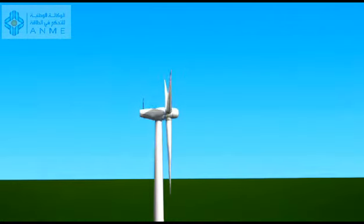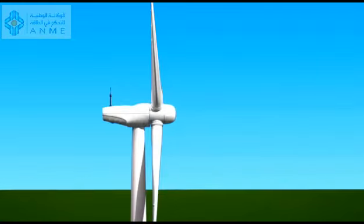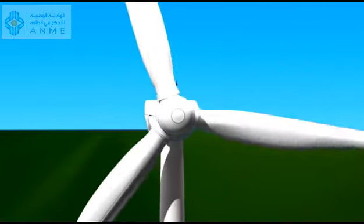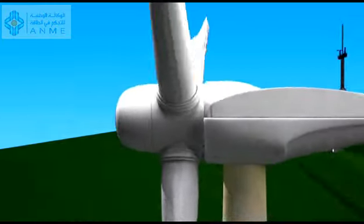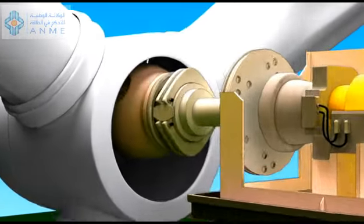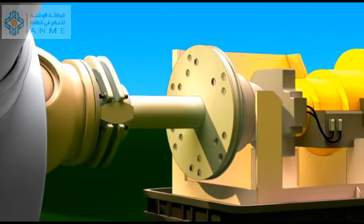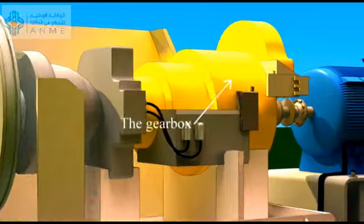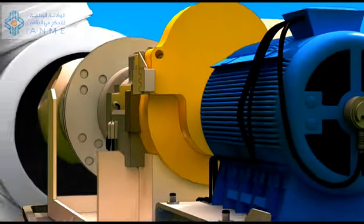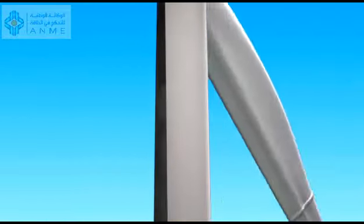The wind turbines are generally equipped with three blades, made with composite materials, fiberglass, carbon. Fixed in the hub, together they constitute the rotor. Powered by the wind, the rotor drives an electrical generator installed in the nacelle by means of a gearbox. This latter allows raising the rotational speed of the rotor from 10 to 20 turns per minute, depending on diameter, until reaching the operating speed of the generator, generally 1500 turns per minute.